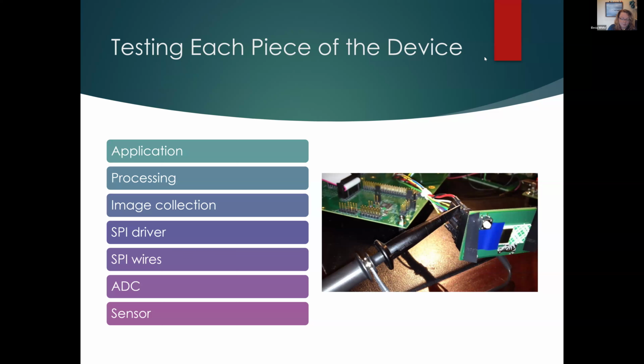Of course, if the computer is 64-bit and the embedded processor is 16-bit, that can introduce its own set of bugs. And how do you identify which pieces should be tested where? If you want to test on the hardware, you can build a widget to inject signals into the communication path, like the SPI wires on the slide. But then you have to debug the widget, which is probably a separate board and processor and a whole other embedded system. It isn't that embedded software engineers don't test their code, but there are so many places where we can test it, and we can often only test pieces of it at a time.